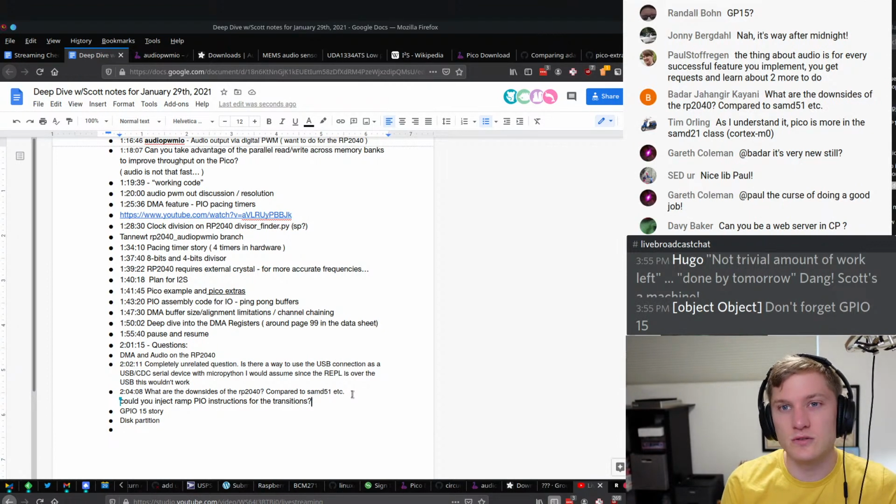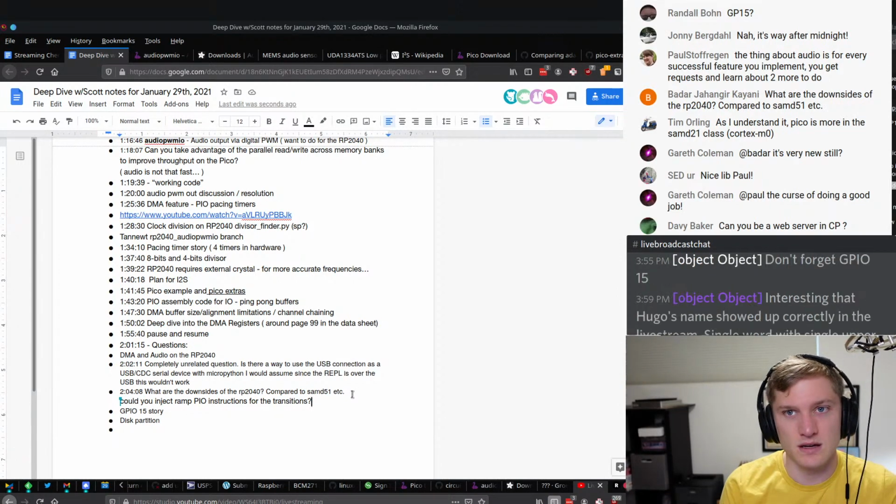So if you need to do very basic things, like take this pin and AND it with another pin, you can do that. But it's leagues dumber than the PIOs are. The SAMD51 also has more pins. If you need a lot of pins, the SAMD51 has more. The RP2040 only has 30 GPIO.